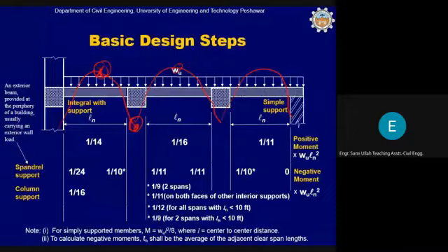So for the design, you need to know the bending moment at the midspan and at the support, and you know that bending moment at the support is negative and at midspan will be positive. So for every span between the supports, two bending moment values are to be determined from the analysis. But if you don't want to do the analysis and use this approximate method, even then you need to know the two values of bending moment at the midspan and at the support.